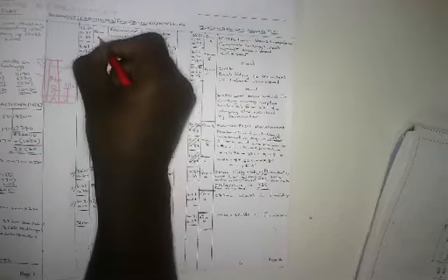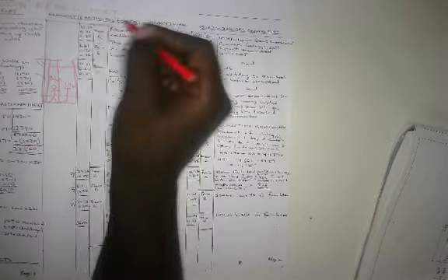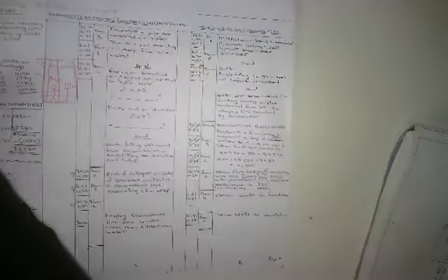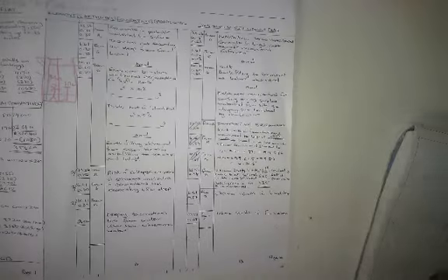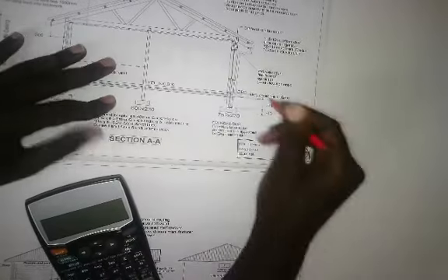So after you've done that calculation, you need to go to A and take the center line for A, that's 35.56, and write that you have taken that reference from your 270 cavity wall, and then multiply it with the depth of your trench. Now how do you get the depth of your trench?